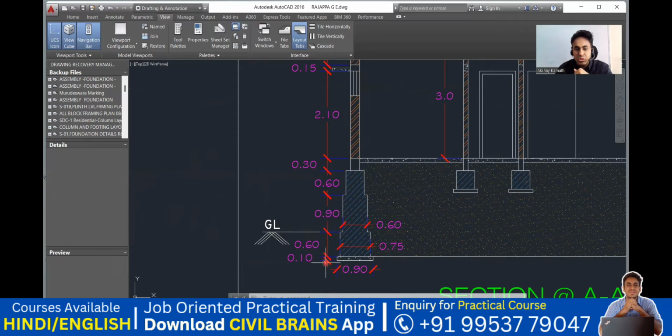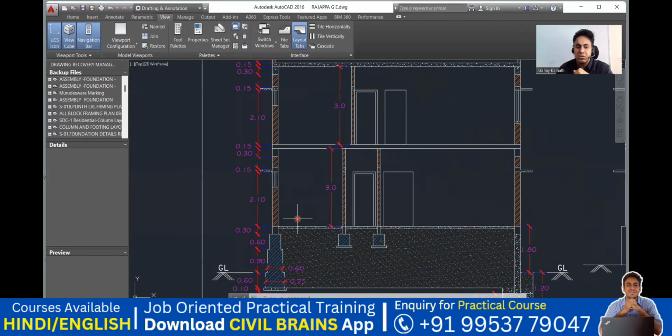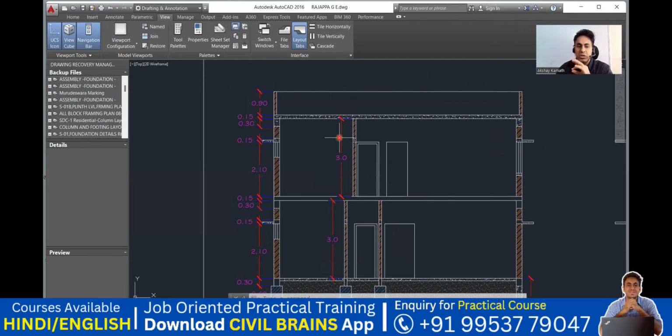From there I'm supposed to do this much excavation, that is 0.6 meter, and then another 100 mm, so 0.70 meter of excavation has to be done. Then my plinth beam will be up to this level. This is my plinth level, 0.90 plus 0.60. This much portion will be my plinth beam, and now my floor level starts. From this floor to this floor it is 3 meter.